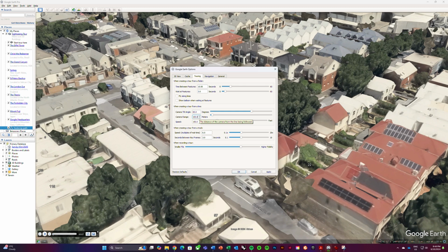We might want to change the camera range, maybe a little bit smaller, depending on the width of your grid. You can span the area the camera is showing, just to make sure that you capture everything and all the details, which will be as helpful as possible. The rule of thumb is the more images that you capture of all the different details in this fly through, the better your 3D model will come out in the end.